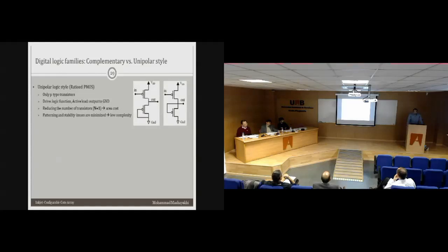The other style is the unipolar style. Unipolar, or ratioed, style is only made of N-type or P-type transistors. Due to organic materials limitations, we only have P-type transistors, in which the load transistor is a fixed one. No matter what the logic is, the load is always one, and it is responsible for connecting the output to ground.